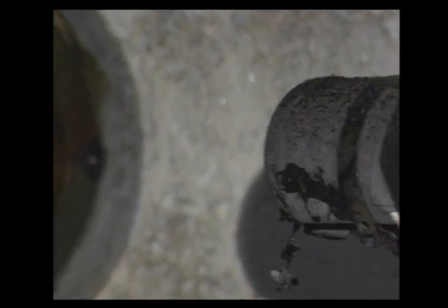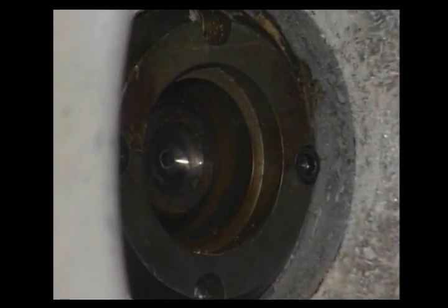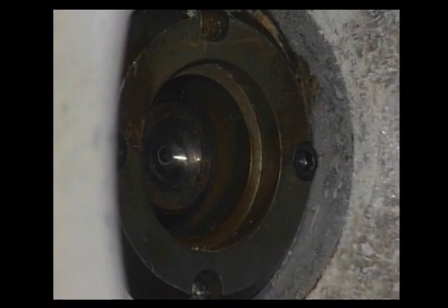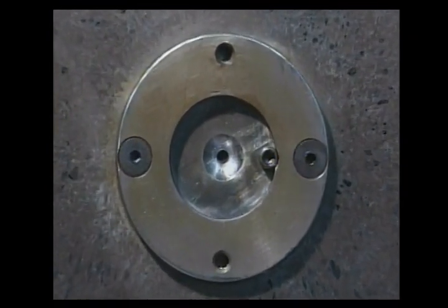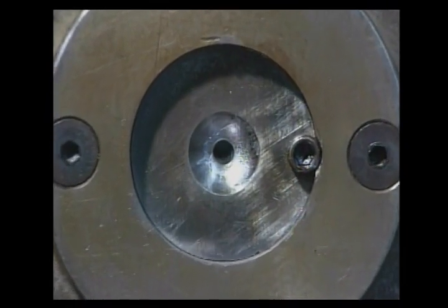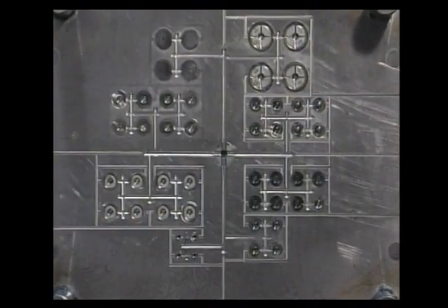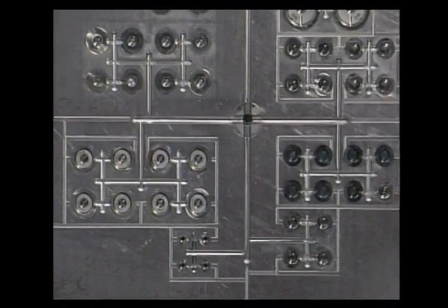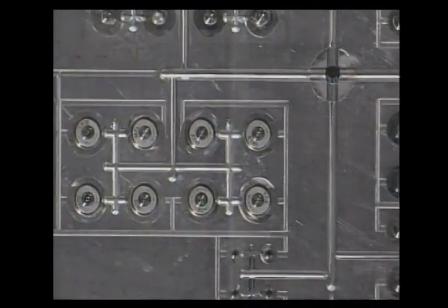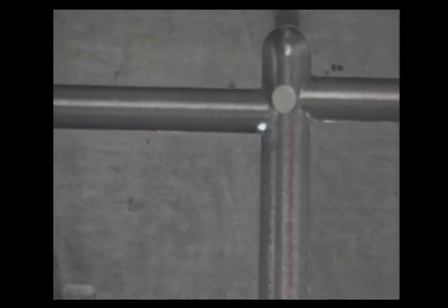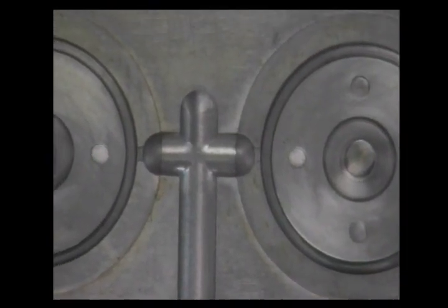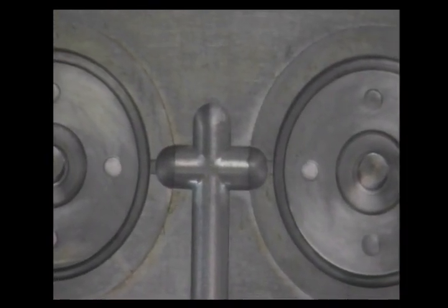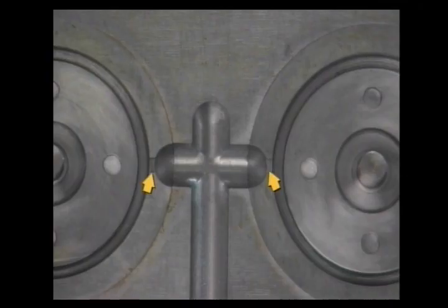The nozzle of the heating cylinder seats on a sprue bushing which is centered in the locating ring. The sprue bushing has a tapered hole in its center. This directs molten material from the injection machine's nozzle into the mold's runner system or directly into the mold's cavity. A mold's runner system is the channel or channels through which the melted thermoplastic flows to reach the gate. The gate is the interface linking the runners to the cavity which forms the part.